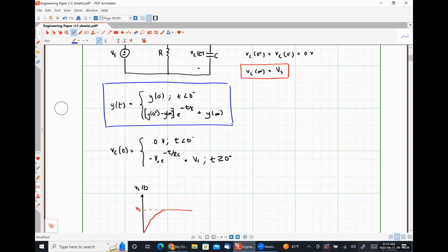We can work example problems if you want, but that's literally the only change that we're going to see. So when I set up our system of 5 steps, and I included step number 3, analyzing the circuit at t is equal to infinity, this is why. Because in a total response problem, it is no longer 0. And so we're actually going to need to know what value our signal of interest has at that particular time to plug into our generic equation.